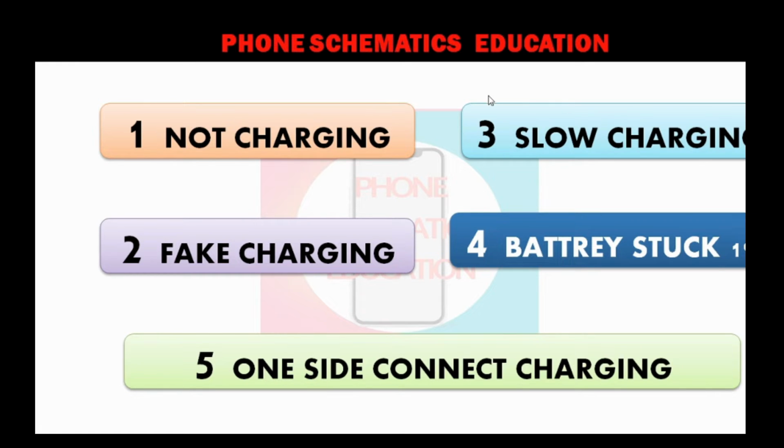So in this video, we will talk about all these faults and how to remove these faults. Now before going to the charging IC, first we revise a little bit about the charging line, PP USB VBUS 5.0 line, right? Remember, in the last video we discussed how this line connects from the charging port to the charging IC, also with the MOSFET connecting to the U2 IC, right?